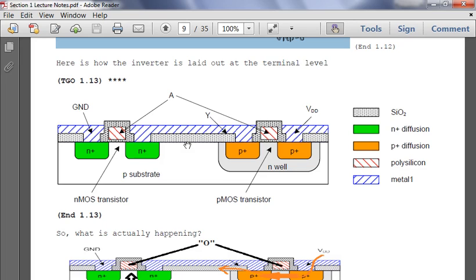But we will get to this whole concept of contact. You're going to have contact here, you're going to have contact here, you're going to have contact here that allows you to actually properly transmit. But you're going to have this here to ensure that you're not having the doped source and drain flowing back up through the polysilicon. You want it to flow this way.